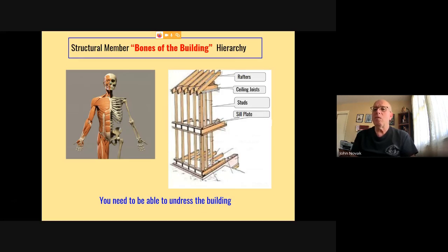Sill plate in Western platform construction. If we have floors, we have what we call a sill plate. So the stud goes down to the sill plate, and then the load is transferred down to studs below, or in this case, if it's a single floor, the studs transfer the load to the sill plate, which transfers the load to the foundation. And again, first floor joists, and if we have a single story building, we just have one set of floor joists.